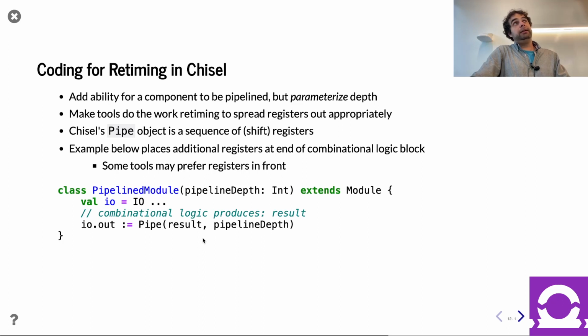Is there a way for the tools to optimally determine the registers? The reason I'm pushing back on this question a little bit is that someone needs to determine the right number of pipeline stages. It doesn't necessarily need to be a human. There are some frameworks out there that are possible for a language like Chisel. If you have a generator with a lot of parameters, this is a parameter. It doesn't mean parameters set by humans. You can have an automated tool flow set the parameters and explore multiple designs for you automatically.